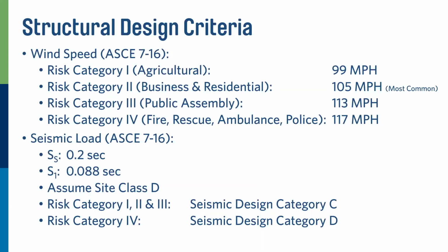I can tell you for all the signs, rarely are we worried about how much it weighs. I'm not worried about it coming down because of gravity. I'm worried about it coming down because of the wind. You see what we design it for. We design it for businesses, residential. 90% of it here is 105 mile an hour wind. This is reduced. It used to be higher in the previous code, so it got reduced down to 105. I don't know if anybody's ever stood out in a 105 mile an hour wind, but you can't. It will blow you down the street.